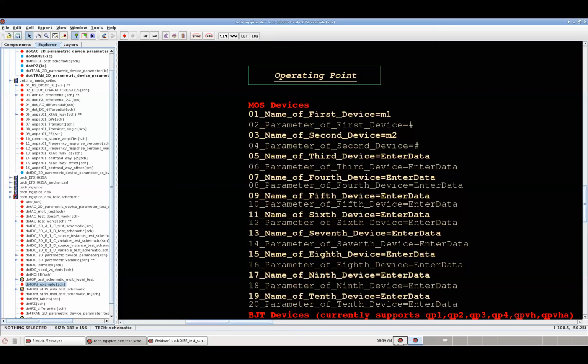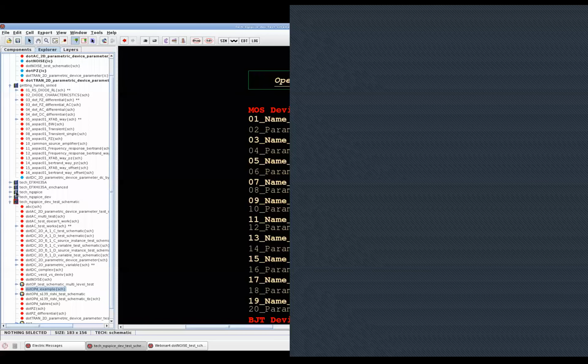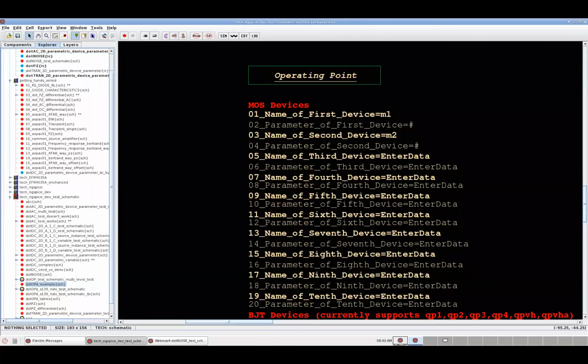Yeah, so are we talking about asking AC analysis not to take the existing DC bias points? I think it takes the DC operating point at the initial run, right? When you just click run for the AC analysis, it solves the circuit at 0 time, and it takes this operating point and solves AC around it, right? Yeah.